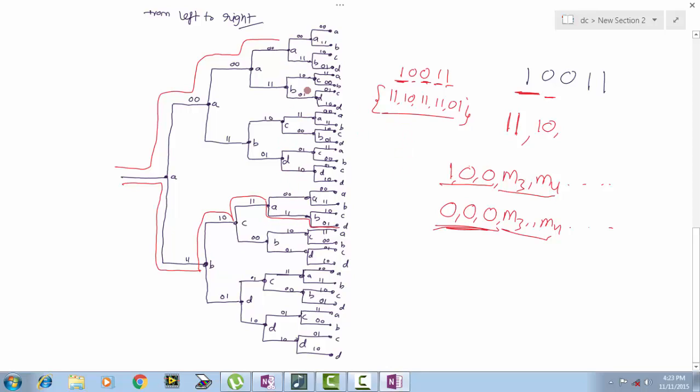As the structure is repeating after 3 branches, we can re-merge those states and obtain a new structure, and that new structure with re-merging branches is called the trellis structure. The trellis structure is a simplified form of the code tree with re-merging branches. A tree with re-merging branches is called a trellis. Next we will look at how to draw the trellis structure for the given encoder, and using the trellis structure we can encode the given message sequence.